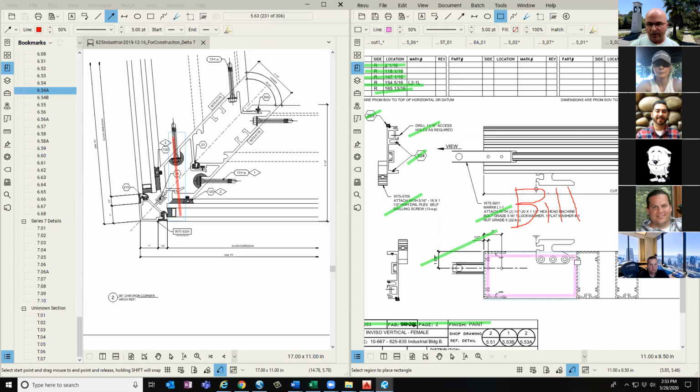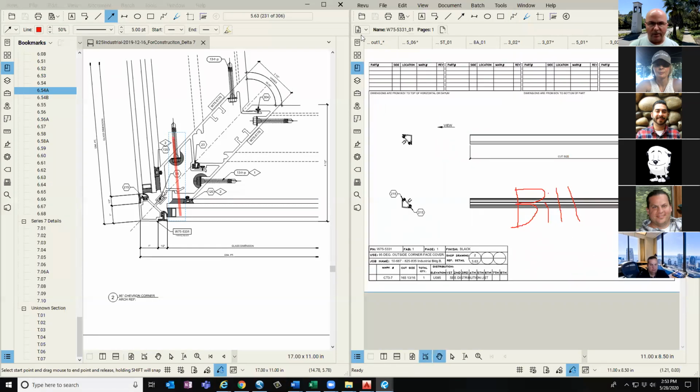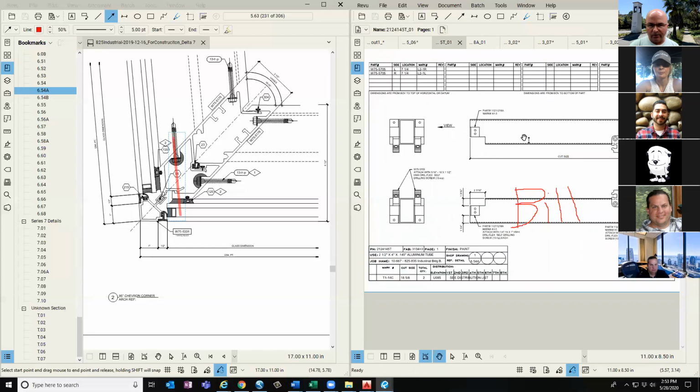So I really want from the top of this horizontal to the top of this to match. So I'm just going to make this deduction, this 154 and 5/16 minus the 147 and 1/16, and that's going to give me the 7¼ that I'm expecting for my pony tube height. I'll verify all of the other things here and finish checking that unit.